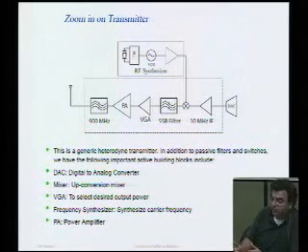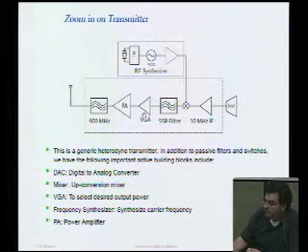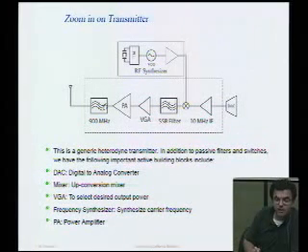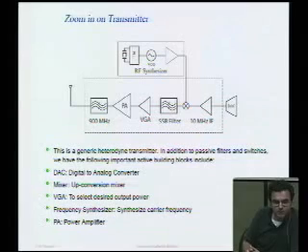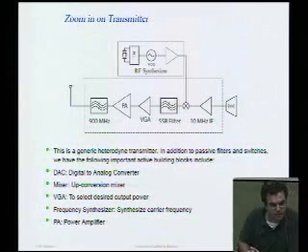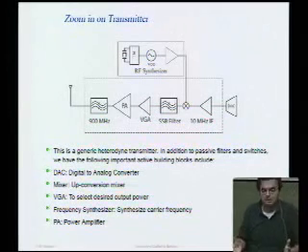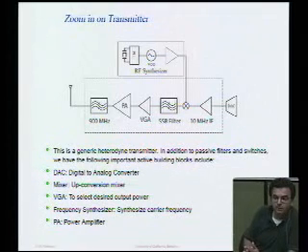And we can also set the amplitude very precisely with, let's say, a VGA, a variable gain amplifier. And finally, we run that into a power amplifier. A power amplifier is designed to put out a lot of power into the load. The load might be the antenna, it might be the cable that it's driving, but usually we'll find the load is a relatively small impedance, something like 50 ohms, 75 ohms, or 300 ohms. If you're looking back to your analog course, most of the loads that you're used to driving are capacitive loads, right? or high impedance loads. In this class, often we'll be driving low impedance loads.